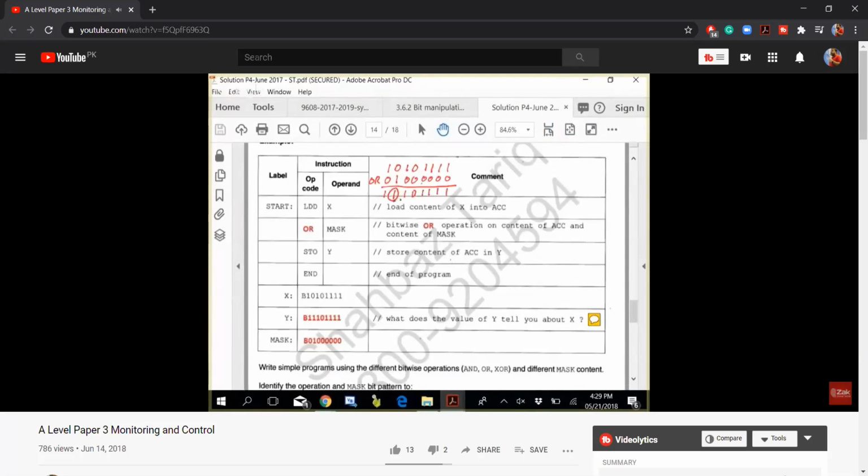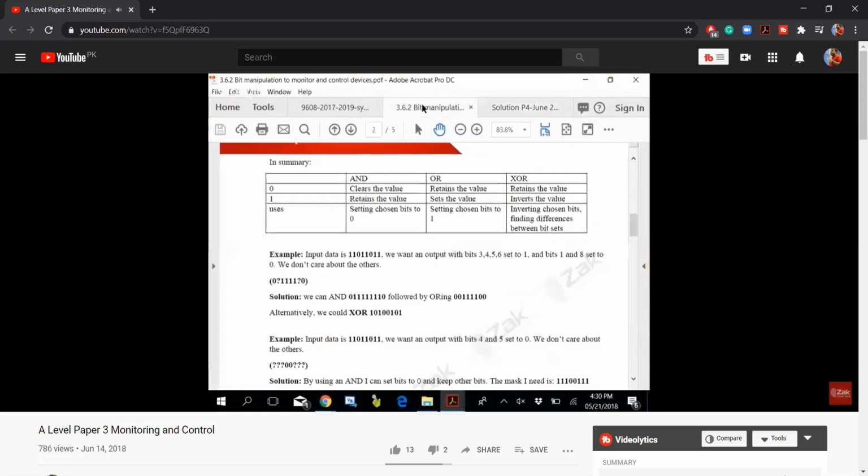Okay. So I am using one bit to set the value of one bit. The operation was OR. What I have done, I left all other bits 0 and just that one bit to 1. When I performed OR operation, that one bit, if it was 1, it will remain 1. If it was 0, it will become 1. So I set it. So that is how we carry out these operations.